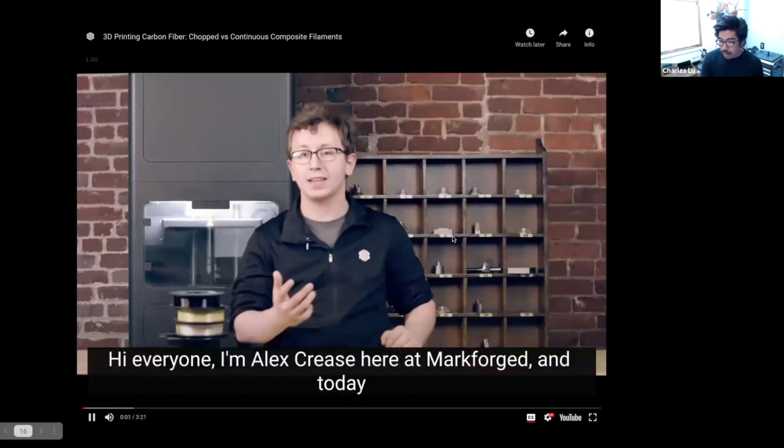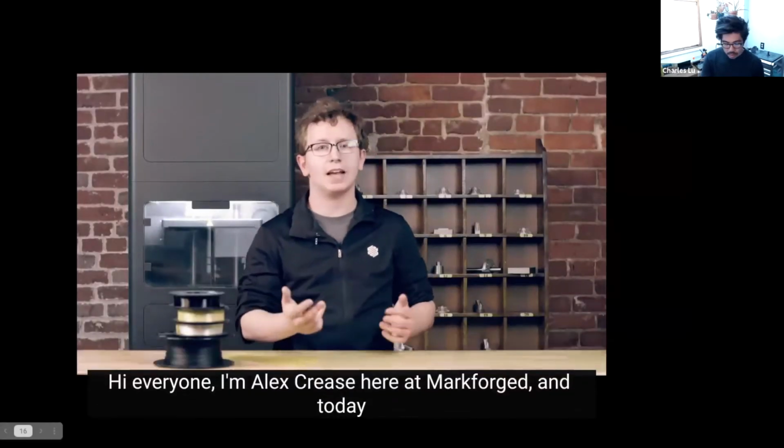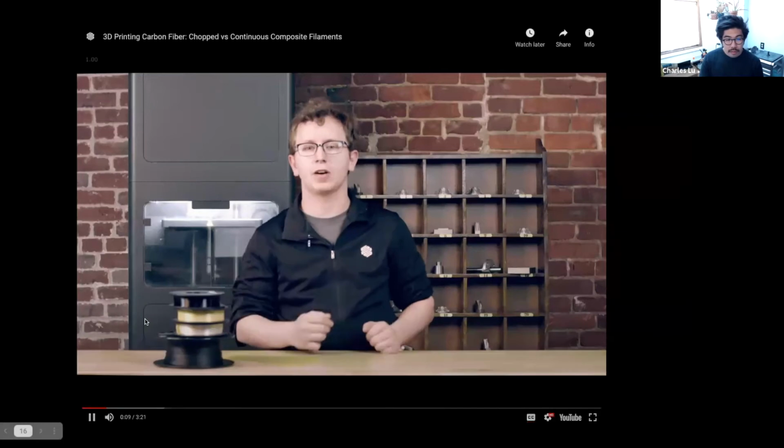Hi everyone, I'm Alex Crease here at Markforged, and today I'm going to be talking with you about the different methods of 3D printing composites like carbon fiber, fiberglass, and Kevlar. When people talk about composites in 3D printing, it can take 2 forms, chopped fiber or continuous fiber 3D printing.